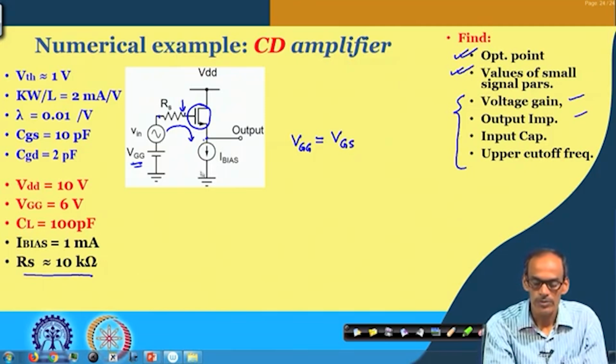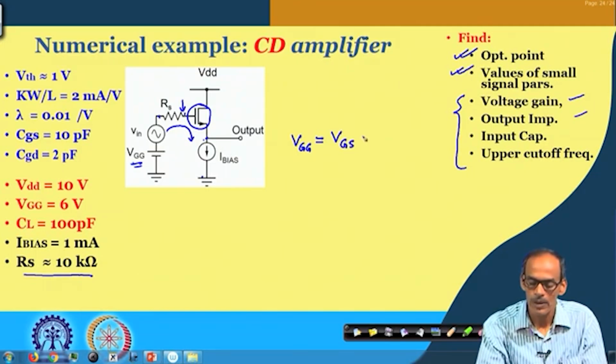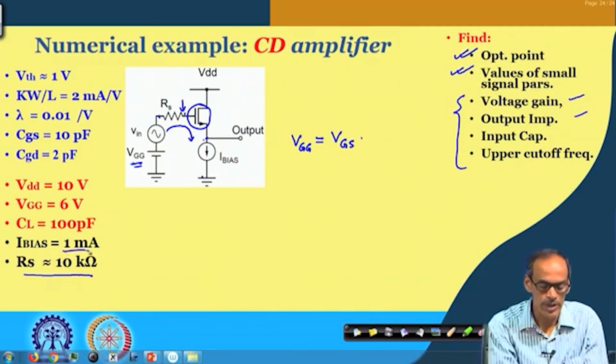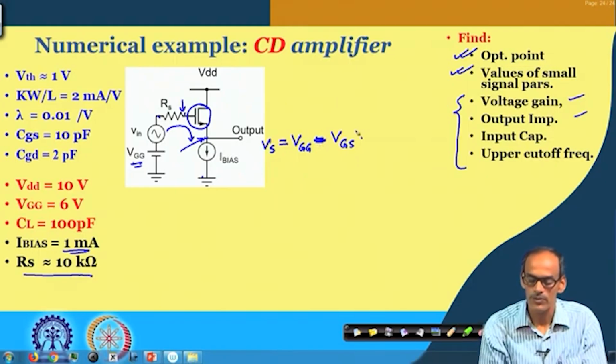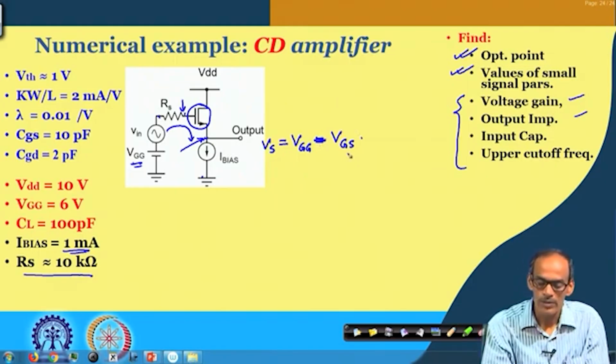And this current flow of course, we do have say 1 milliampere of current. So, we are expecting to find the voltage here, which is basically Vgg minus this one, sorry, I should say that the Vs voltage or V out voltage is Vgg minus Vgs. Now, to find the Vgs, what you have to do, this is now IDS.